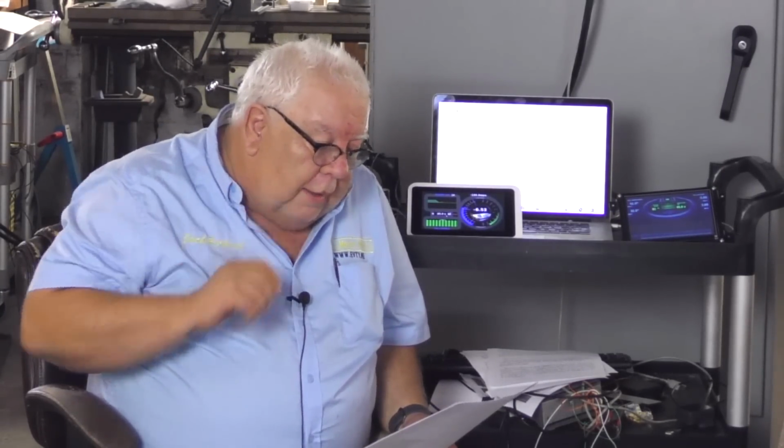Tesla superchargers recently have gone to 120 kilowatts, and at 400 volts, that is indeed 300 amperes, but you only need to do that about 40 minutes to completely charge a completely empty battery. So we got a little difference between 15 and a half hours at 110 amps and 40 minutes at 300 amps. And this brings us to the real issue, which is heat.